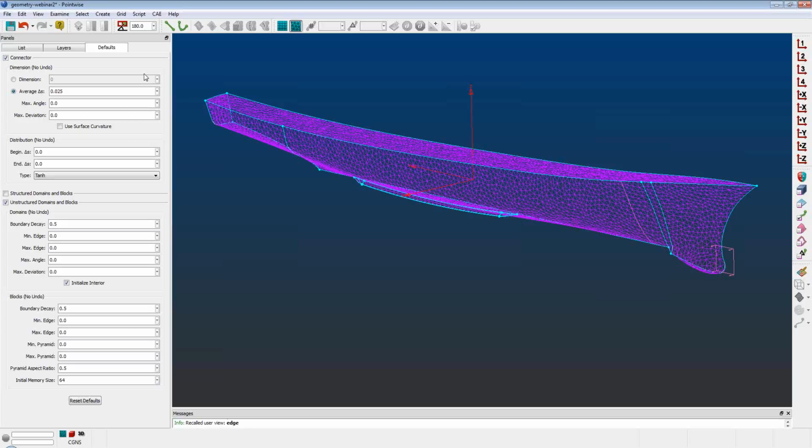It's really just a visual thing, like I said before, with the model assembly of the solid models. It's not modifying the surface, it's just creating the glue across the gaps. And so, the larger you make that glue across the gaps, the more you start getting unwanted behavior. So really, it's just for general sloppiness, not for actually fixing missing geometry. If there's grossly overlapping geometry, you're probably going to need to fix it, like I did with the overlap surfaces. But if there's just general sloppiness, and those errors tend to be, like I said, several orders of magnitude lower than the overall model size, those are appropriate for healing up with the model assembly and the mesh merging. Okay, thank you. Thanks.